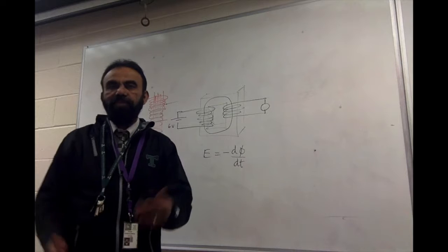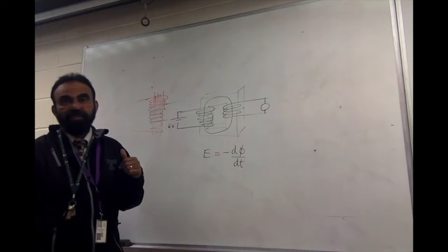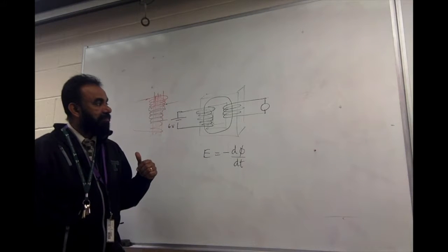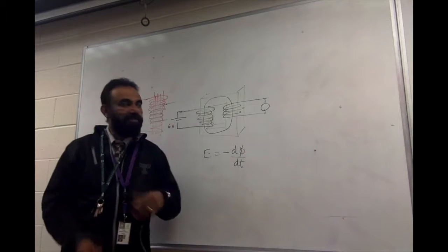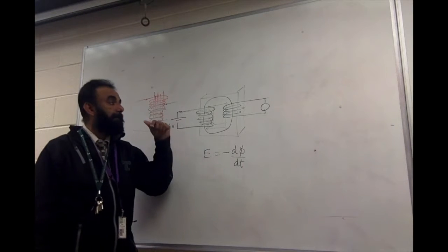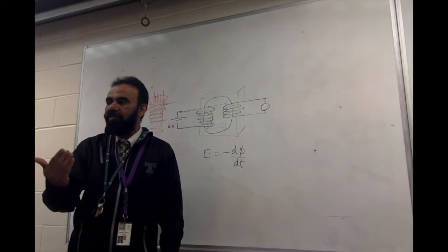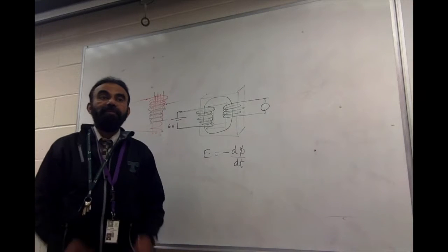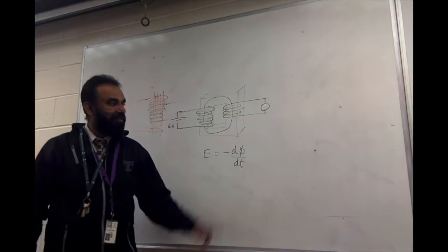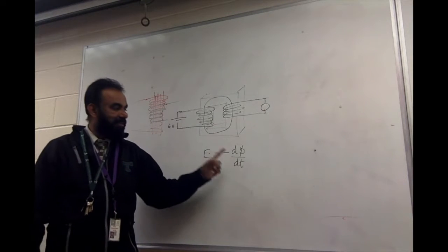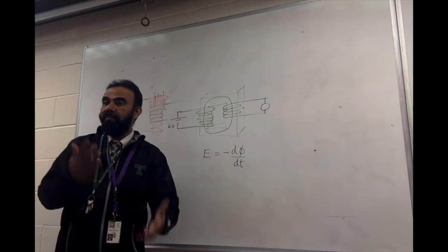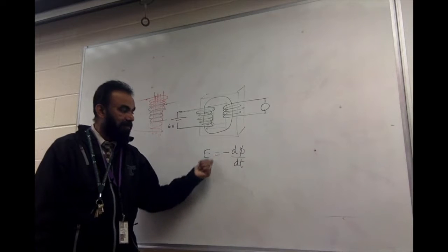It is something that is commonly said in physics, especially in a transformer or any induction device. The EMF at make, which means when you make the circuit, the EMF induced is much smaller compared to the EMF at break. Because when you break the circuit, the rate of change of flux is very high, so the EMF will be much higher.